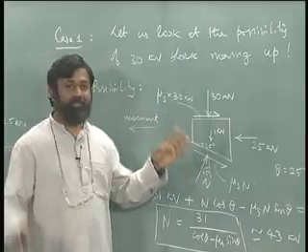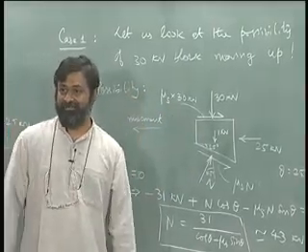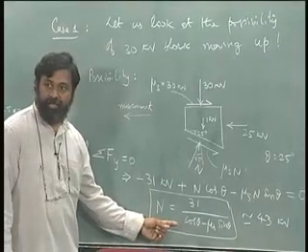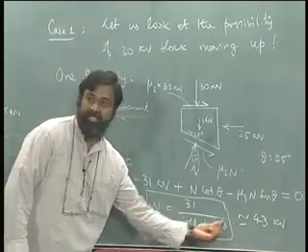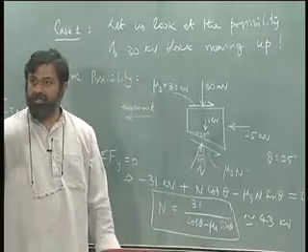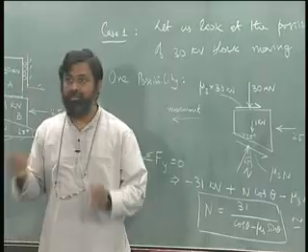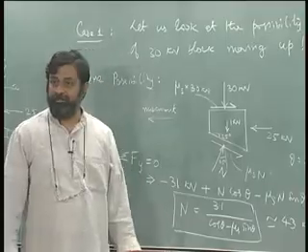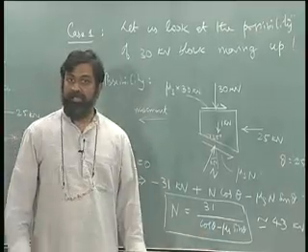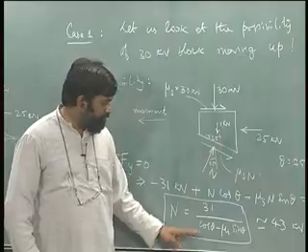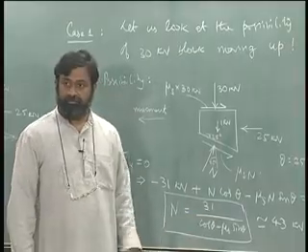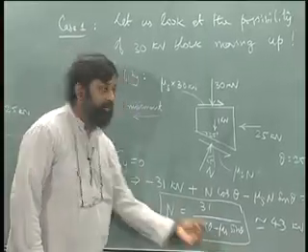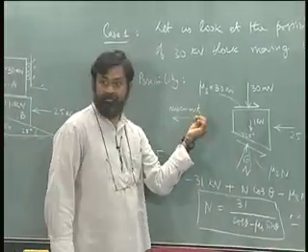The direction of frictional force are the only ones that will change, right. The direction of frictional forces will affect to a certain extent this normal reaction, but remember mu s times sin theta is roughly around 0.5 times 0.3, around 0.15 or around 15% is what its contribution is, okay, and cos theta is roughly around 0.7, and therefore the major effect is due to this cos theta, okay. Now the reason why I am putting this here is there will be a plus sign coming the moment it is the other direction, alright.